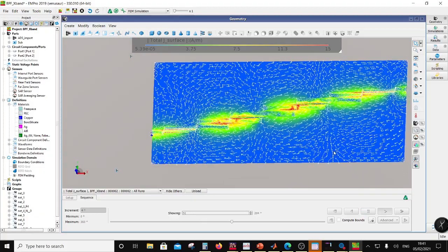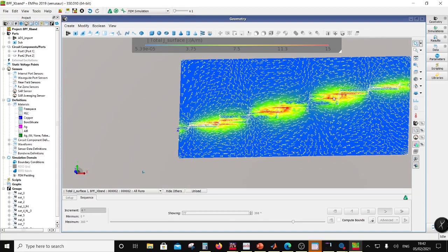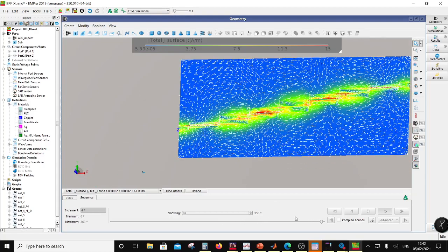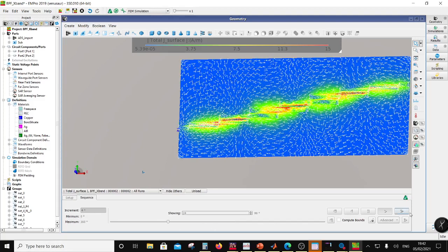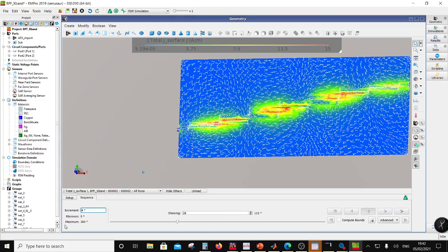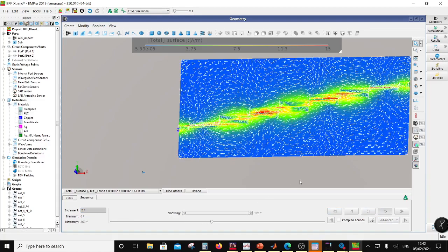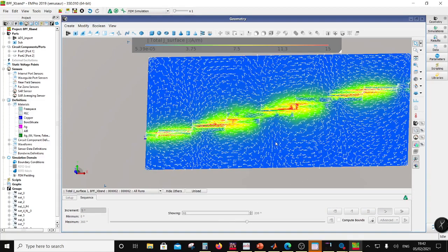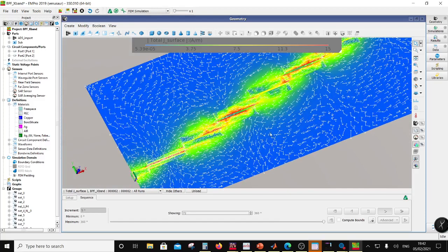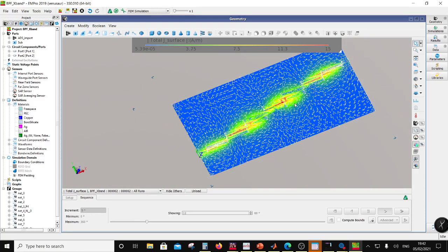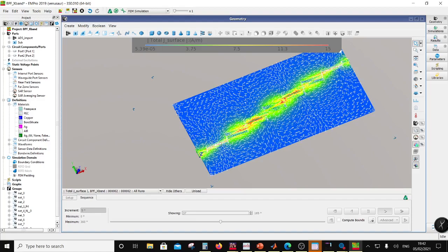Okay, so what you're looking at is this filter, and why is it going 90 degrees only? Okay, let's make it faster. This is too slow. 5 degrees. Okay, play. So this is what is happening to currents in the ground plane and also the coupled lines. You can see what is happening to the coupled lines, and this is multiple wavelengths long, right? Because just one section is lambda by 2, so these are multiple wavelengths long.